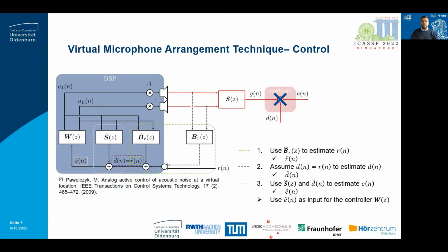During the second stage, called the control stage, it is assumed that the measured acoustic paths remain more or less unchanged after removing the probe tube microphone. The measured acoustic paths S hat and B hat are then incorporated in the ANC algorithm as internal models to make online approximations of the sound pressure at the eardrum. This is done by following a three-step approach.